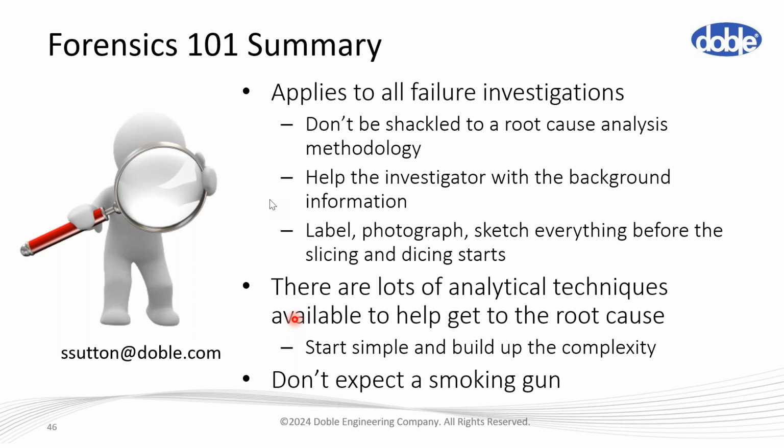Wow. Does thumping potentially cause other damage? Yes and no. You're not normally thumping the cable with a particularly big voltage, but it depends what type of damage you might expect to have in the cable. So if you have water trees, then in a medium voltage cable, water trees are more likely to convert to electrical trees if they see voltage transients like thumping.